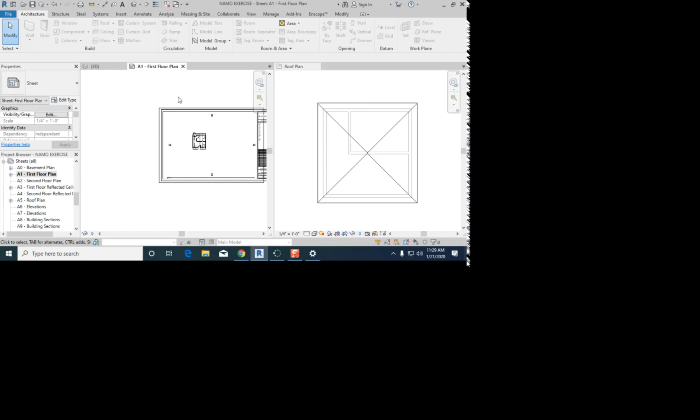If you have 3 windows or 3 objects, and you want to quickly equal their dimensions, do you click on the objects or do you click on the dimension string? Dimension string. This is something I'm still learning. I still always want to click on the object because that's what I'm used to, but yes. Okay. Here's another bonus content, 2 more.